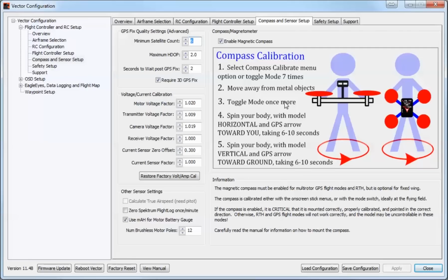You don't have to do this every single time you fly. There are mixed views on this one. My personal opinion is if you can calibrate your compass in or around the general location that you fly, and when I say in or around, I mean within 100 miles of that location, and then you can store your aircraft where you aren't sitting it next to magnets or anything like that that could cause interference with the compass, there's no reason that you should have to do this compass calibration every time. If the compass goes out, you will actually get a warning. The OSD will give you a warning saying compass needs calibration, which is a really nice feature because it's something that doesn't always happen with multi-rotors. So just bear that in mind.